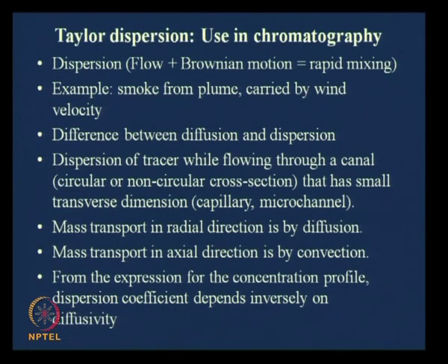Okay. Now, what you take into account while defining the governing equation is that mass transport in the radial direction is by diffusion, and mass transport in the axial direction is by convection, because in the axial direction there is a flow, right.